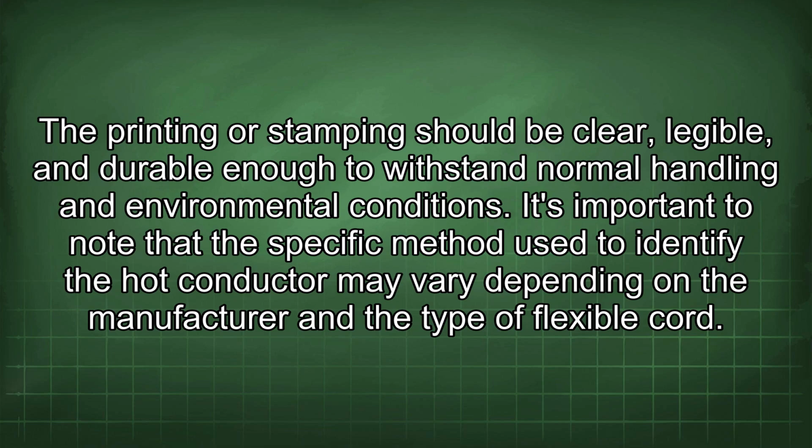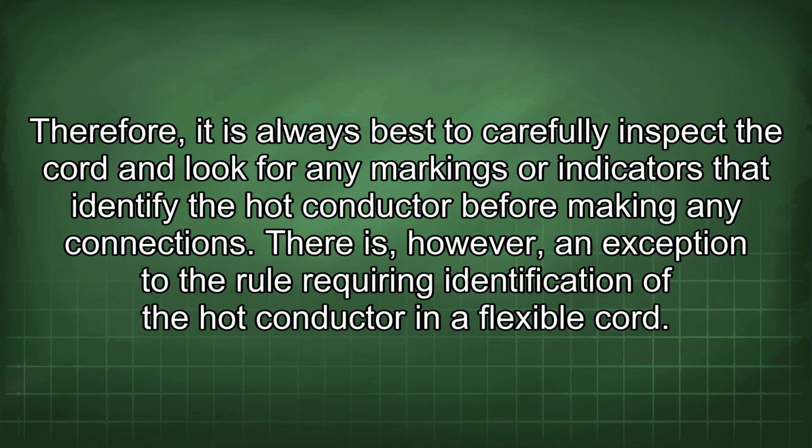It's important to note that the specific method used to identify the hot conductor may vary depending on the manufacturer and the type of flexible cord. Therefore, it is always best to carefully inspect the cord and look for any markings or indicators that identify the hot conductor before making any connections.